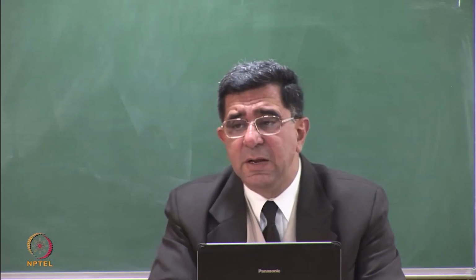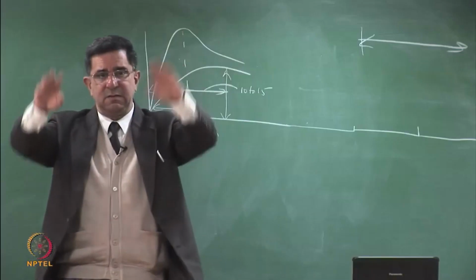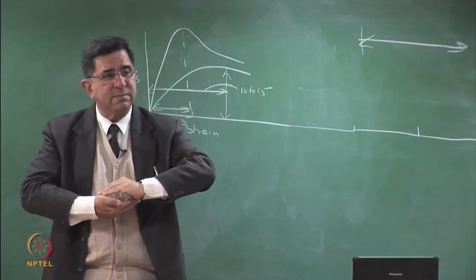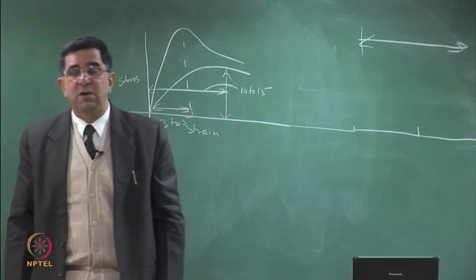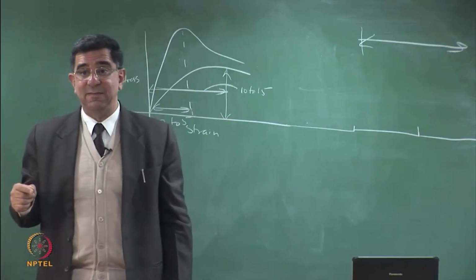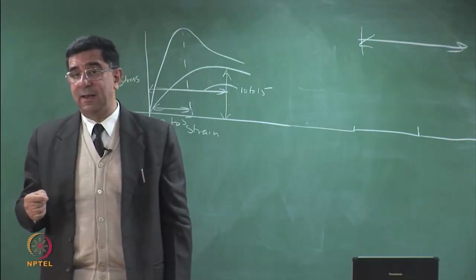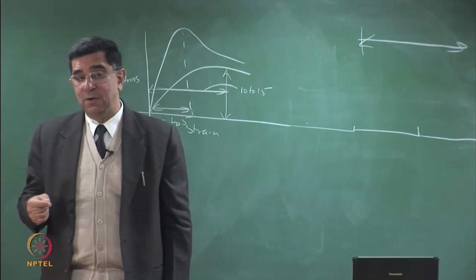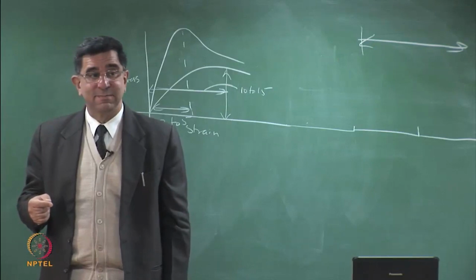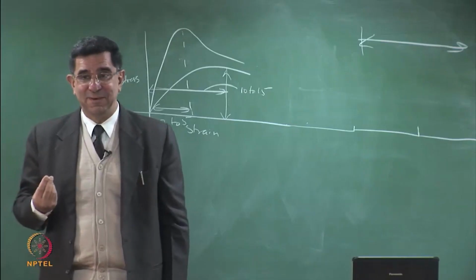So the question being asked is, if you are doing the dual hot wedge welding, and the two rolls are going like this, and I am welding like that, and I apply air pressure and I find that the air pressure is not sustaining itself, how do you find a leak? How do you find a leak when your cycle tire is punctured? You put it in water and bubbles will come out, bubble, bubble, bubble, right?